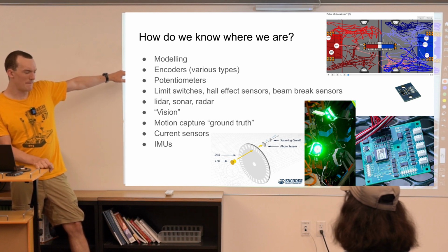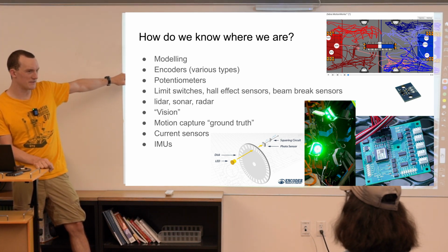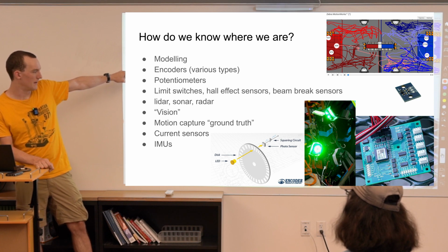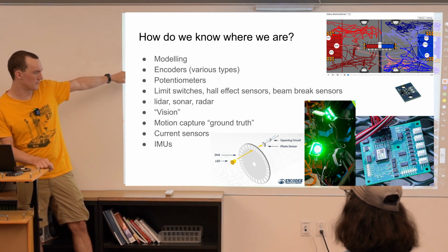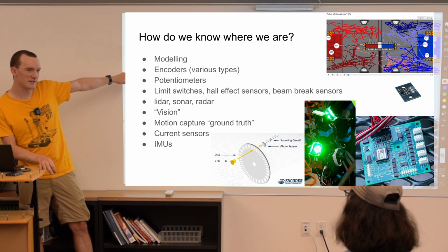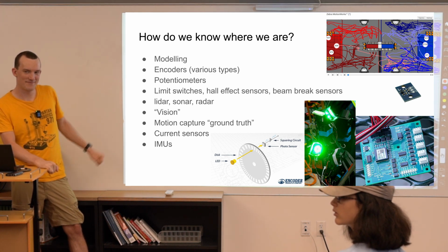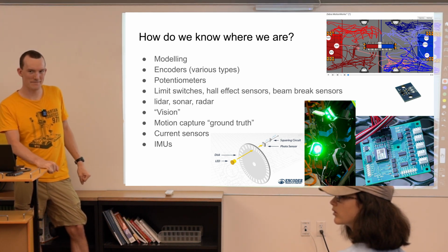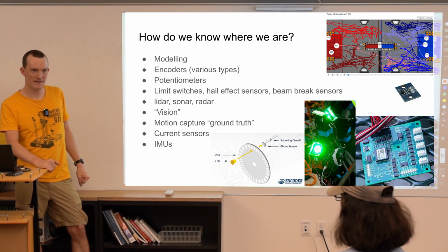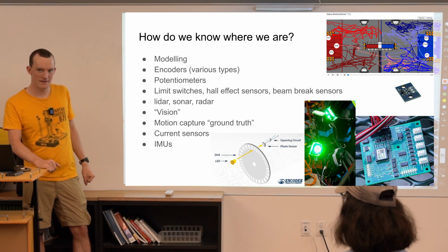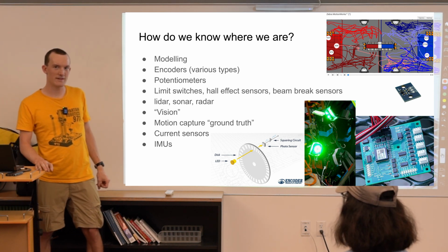I'm actually going to jump back to encoders in particular, since they tend to be very relevant for how these things work. Can anyone here describe to me how an optical encoder works? You have a disk with various cuts in it and an LED. The LED shines through the disk. There's a photosensor. There's a squaring circuit, and you read the output, either PWM or otherwise.